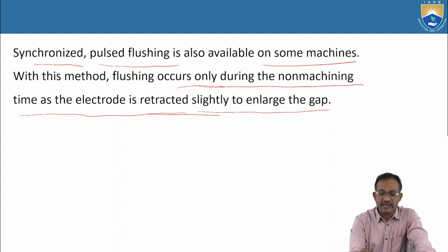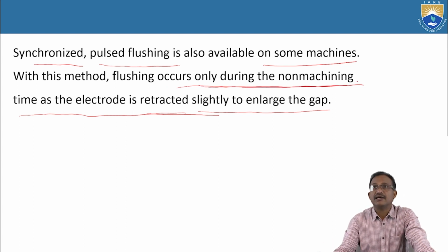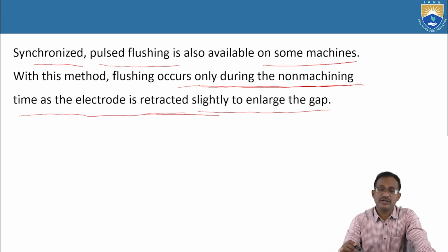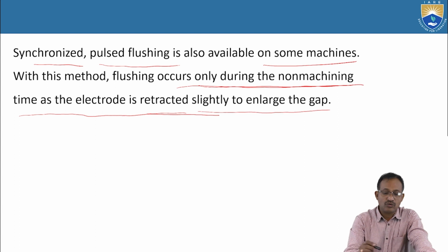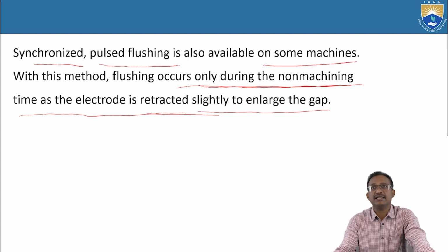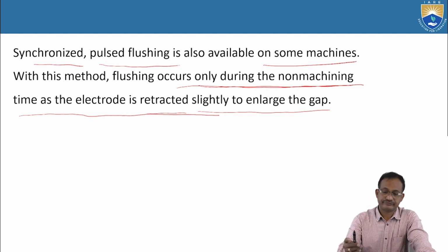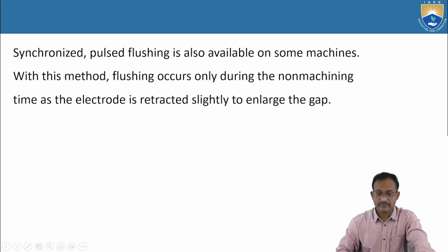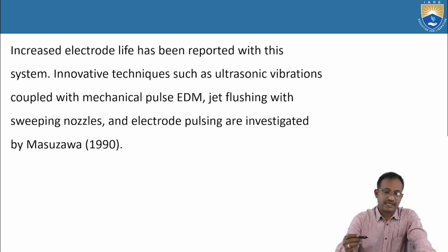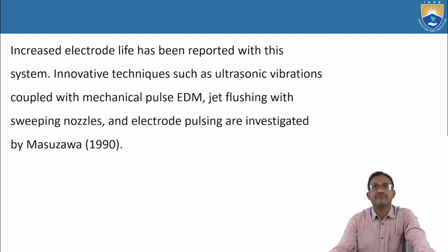Flushing occurs only during the non-machining time. During machining time, it will not affect. During non-machining time, the electrode is retracted slightly to enlarge the gap. Next, increased electrode life has been reported with this system.